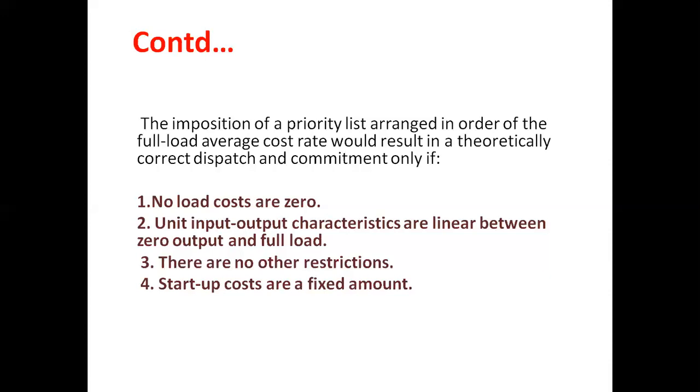So these are the conditions in order to obtain the correct dispatch using the priority list arrangement. Those conditions are: no load costs are zero, unit input output characteristics are linear between zero output and full load, there are no other restrictions, and startup costs are a fixed amount.